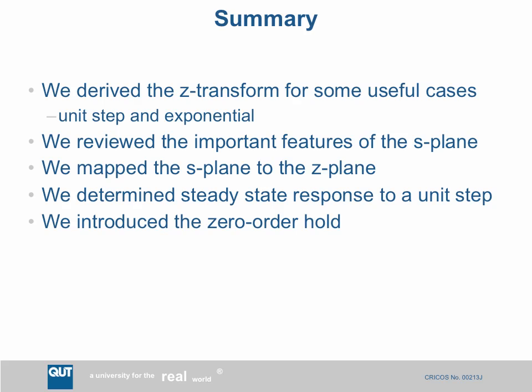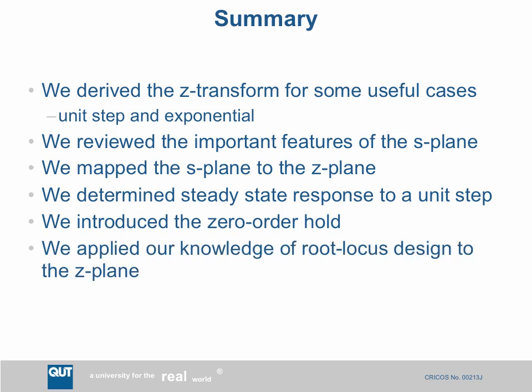We introduced the zero order hold, which is important when we connect a digital compensator to a continuous time plant. And we applied our knowledge of root locus design to the Z-plane. So we designed a simple compensator, we looked at the root locus, and we looked at the step response.